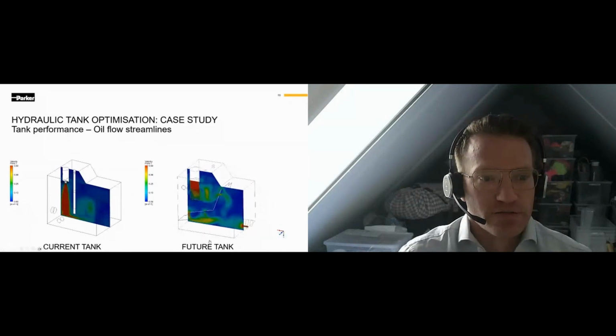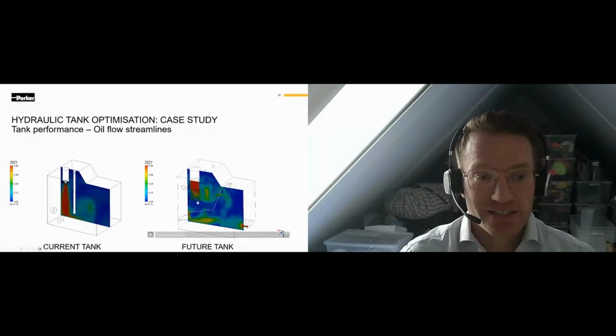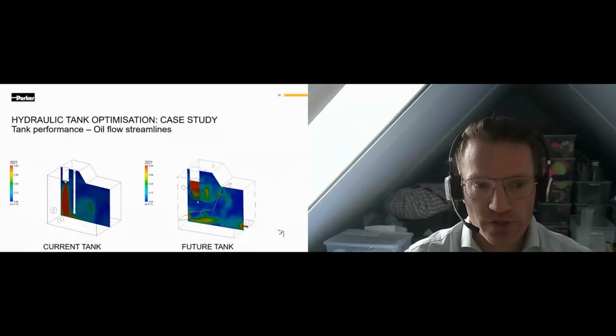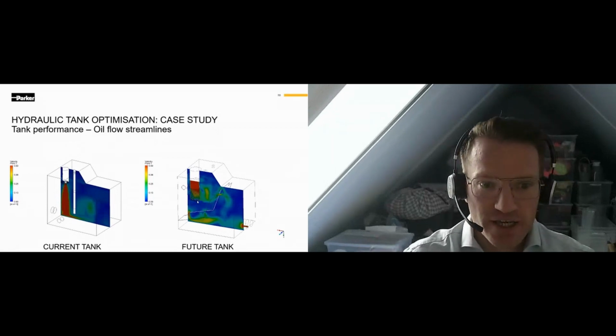So here you can clearly see that the flow velocity of the oil that is released into the tank is much lower compared to the current tank situation. Again, that's improving the deaeration and minimize air contaminations going into the suctions.